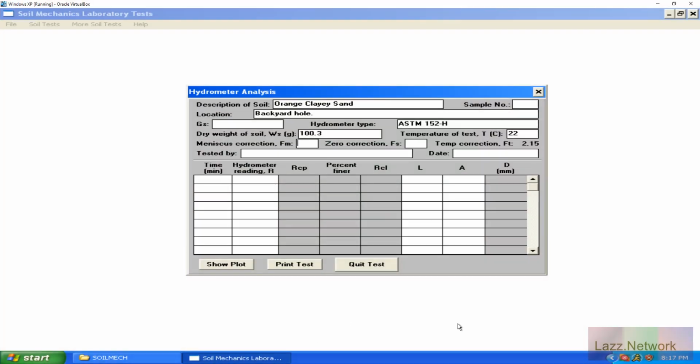When you calibrate it, you'll do it at a temperature gradient that your facility can maintain. So if your temperature gradient is anywhere from 20 degrees to 25 degrees Celsius, then you want to make sure that you hit those points. It's anywhere your hydrometer is going to be exposed to that temperature, because it's going to change the density of the water. So if the density of the water changes, then your hydrometer reading is also going to change with your sodium hex solution that's in there.